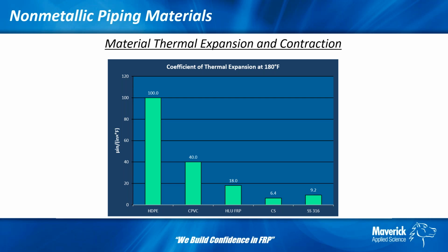Because of this, in the last few years, particularly the thermoplastics, like say HDPE or PVC or some of the others, are being analyzed more and more because they're going into more demanding chemical processes. So they need to be scrutinized more to assure that they're going to perform as expected. So we're seeing these systems being analyzed with greater detail, even with formal pipe stress analysis programs.